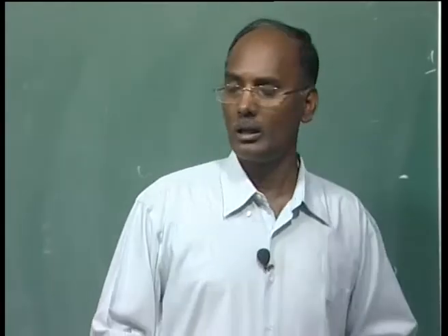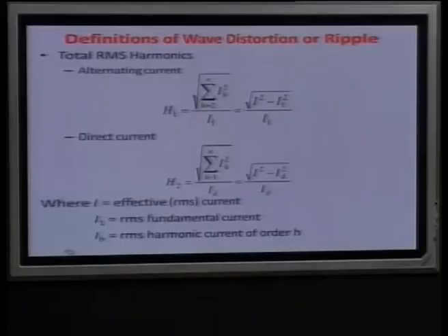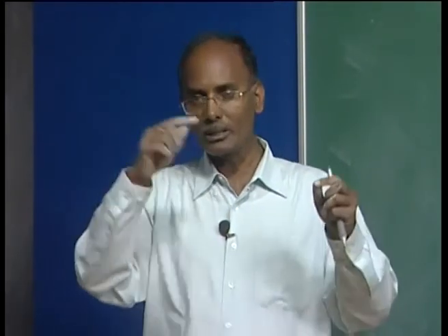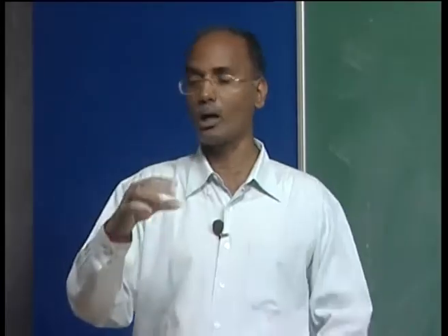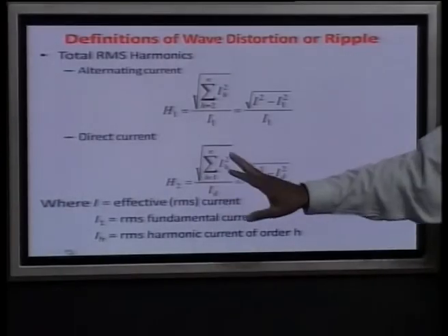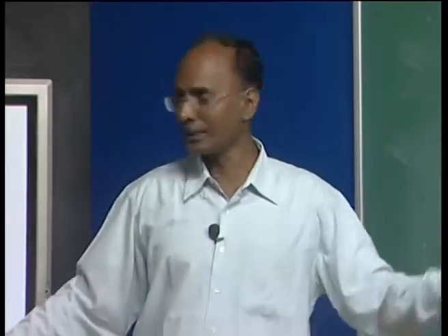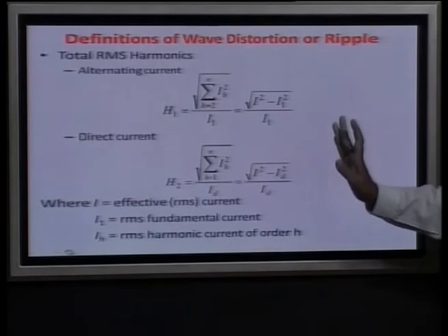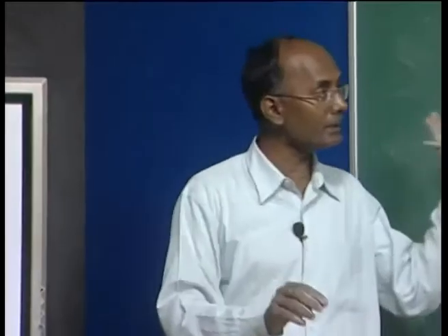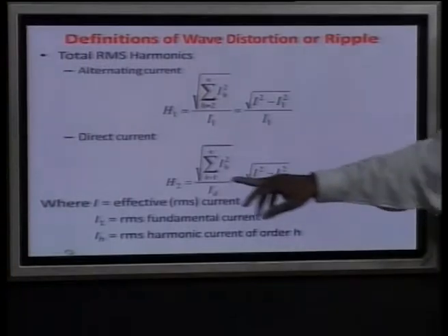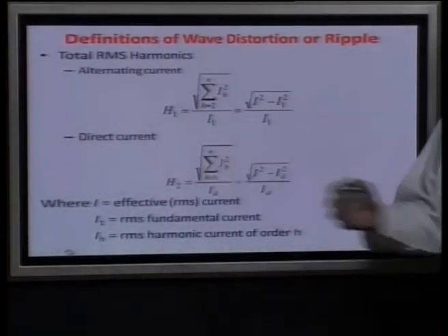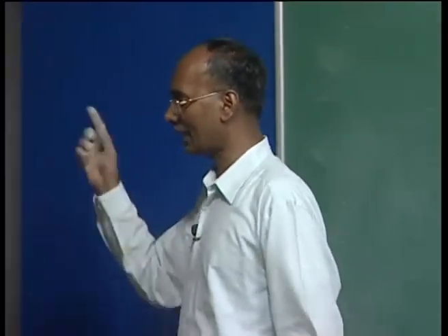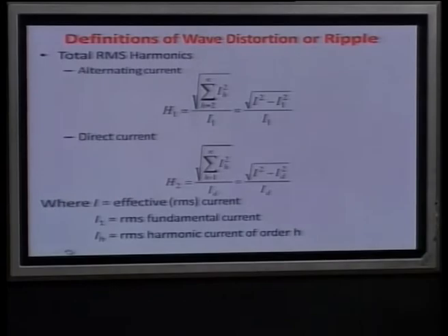The DC side current is constant, it's the average here. Now normally we want the DC to be ripple free, but it is not so. There will be some changes in the current, no doubt, but how much this value H2 is there is a deciding factor. For the analysis we said that the DC is constant. If the DC is a fixed value, ripple free, this value will be 0. Means we analyze the component with the assumption that H2 is 0, because this value is not there. We assume this is ripple free, but it is not ripple free, it will have some component, and based on that we can analyze and find what the value of H2 is.